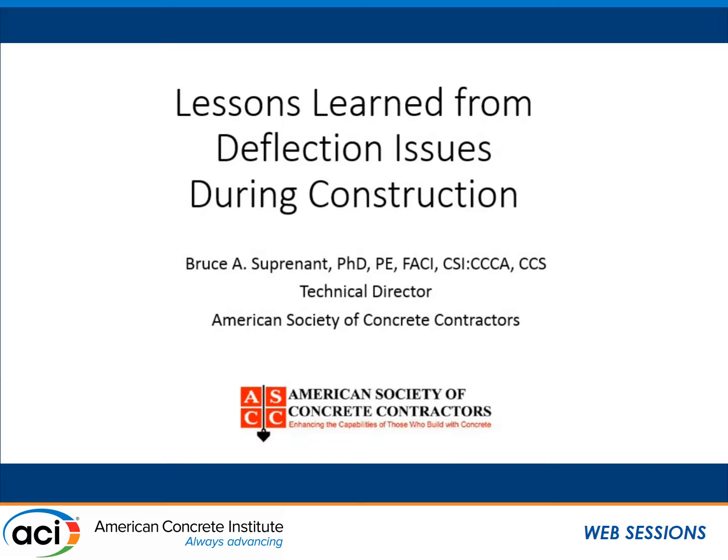Modulus of elasticity, I used to own a testing lab. Our problem with that is, from an engineer and contractor side, we love to see it on differential shortening or column shortening. Depending on the building size, on column shortening, modulus of elasticity, creep, and shrinkage, right, is what you'd like to see measured. West Coast, prone to earthquakes, we've seen some measured there. Our big problem with the owner is not necessarily the testing when the job's going on, because what's a couple hundred dollars for modulus of elasticity? The problem is, if you want to use it in design, you've got to collect that information a year or two in advance.